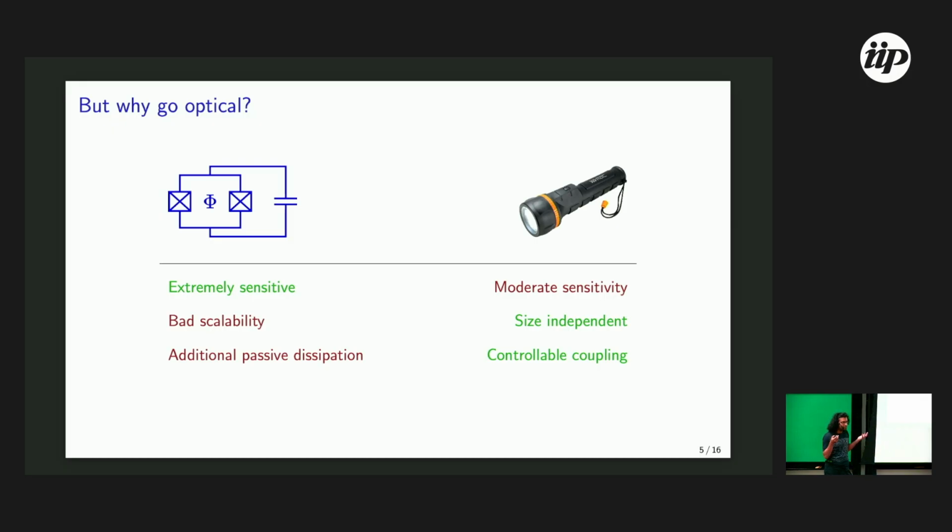But a transmon is still built out of a microwave circuit, so it's not going to be as scalable as, for instance, an optical system, which you can take down to even sub-diffraction limits and much lower. There's another point: because you're always coupling a system, it typically leads to additional dissipation. You cannot control the dissipation that easily. You can tune the frequency of the transmon, but normally there's always additional dissipation by at least the microwave cavity surrounding it.